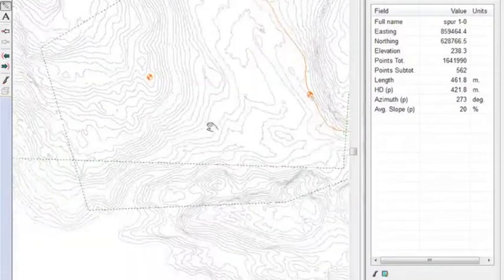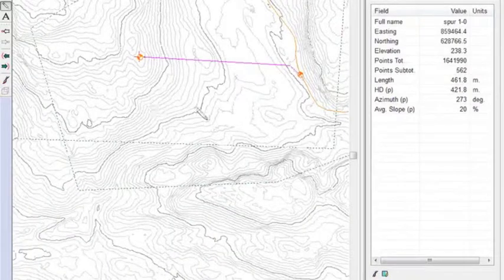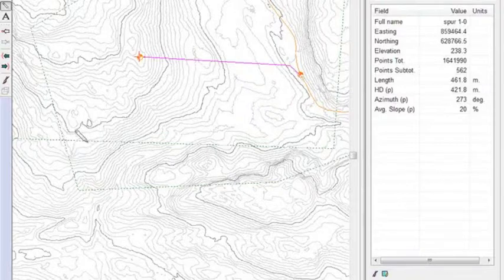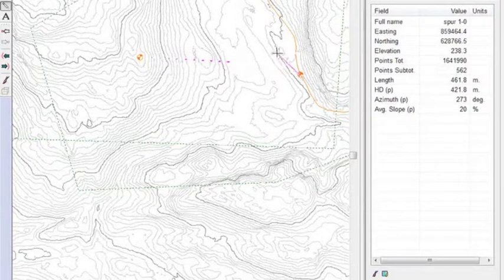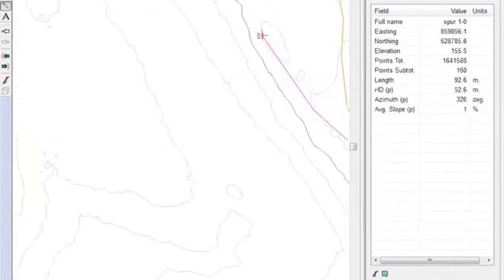It looks like there's a good spot for a switchback. I think it's over here. Let's just see where we go. Pegging kind of leads you along. So here we go, we're going to go down the hill. 16%, too steep. Back up a bit. 1%, not steep enough. Okay, how about there? Minus 4, minus 10. That looks reasonable, and that's a 50-meter leg.